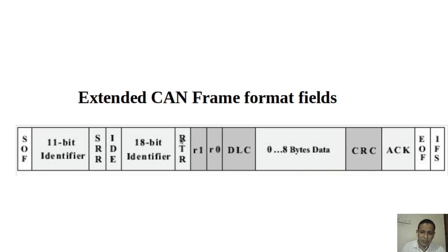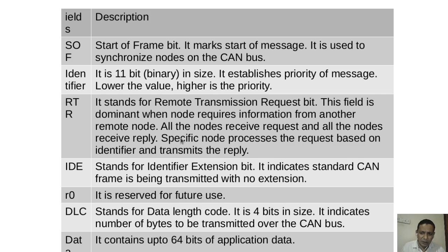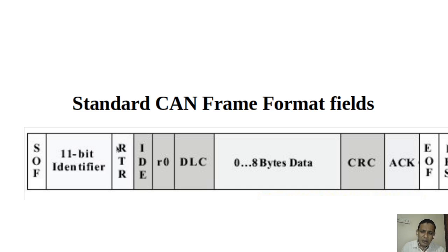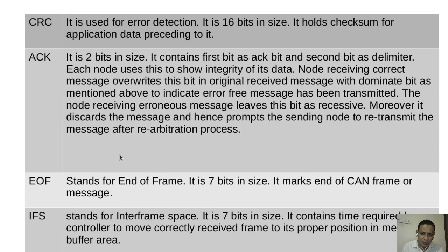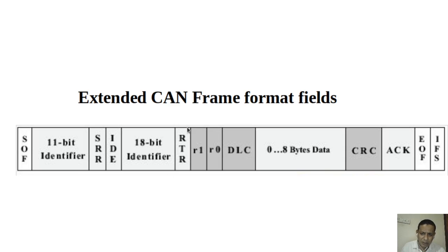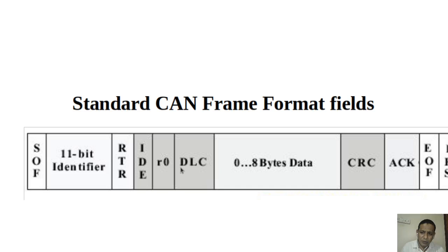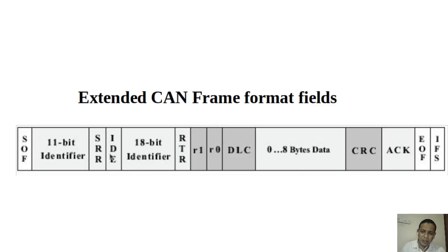But in the case of the standard frame format, RTR comes after the 11-bit identifier. So in the position of this RTR, this SRR will come.